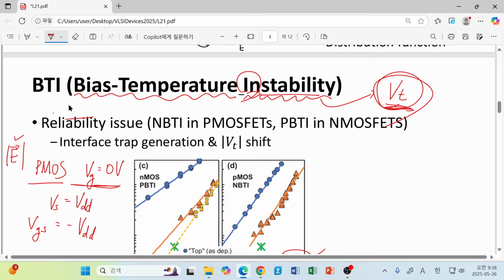Usually the tendency is that the absolute value of our threshold voltage goes up. Previously the device was well turned on and turned off. However, 10 years later, after severe operational conditions, it does not conduct as expected, because its actual threshold voltage is increased in terms of absolute value. So at a given VDD value, it is not strongly turned on.